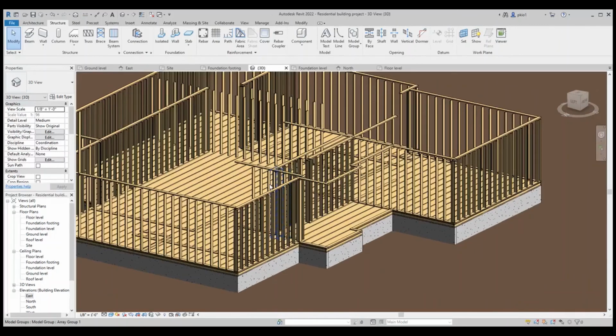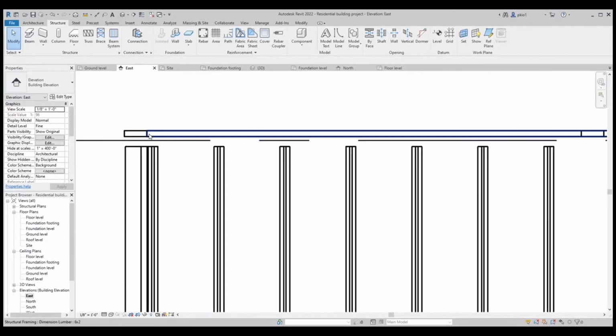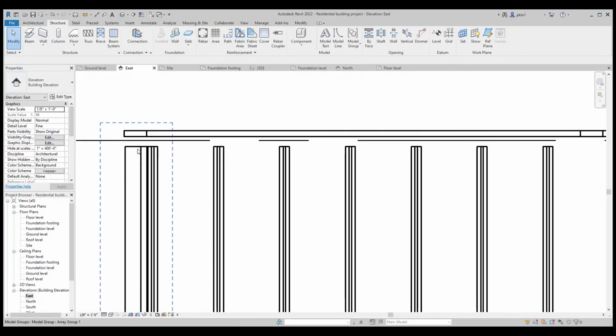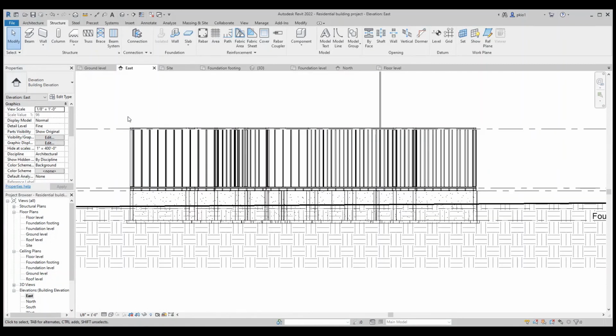It shows example of some top plates. And we want to see how it laps. So go to this elevation and check it out. You see that these top plates are far above. They already set the studs to end below the roof level so that we can adjust the top plate. So we select the top plates and adjust, set Z justification to 0.